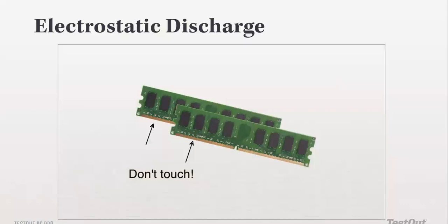We said previously that while working on PC components, irrespective of the fact that you are discharged, do not touch these electric pins. Reason being that there might be a very minute amount of electricity in you that you cannot feel, which can easily damage these components.